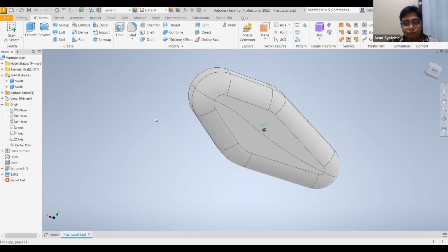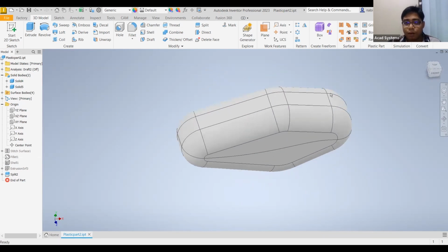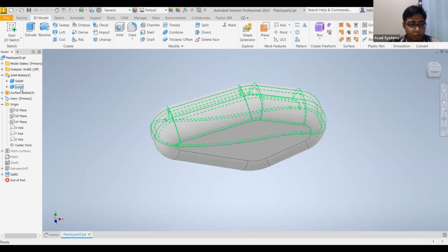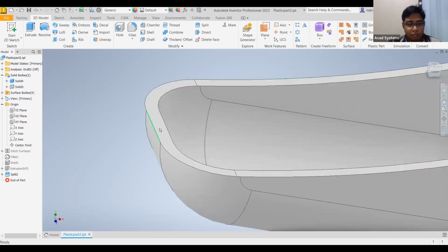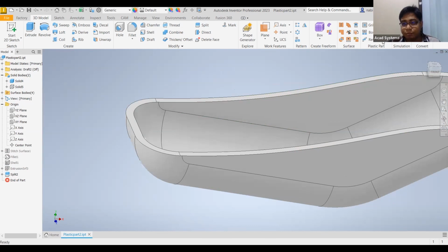Now that we have this cut into 2 areas, I'm going to apply the plastic tools. For example, I'm going to add connections so that this one can be snapped into the top of here, so it will be snapped together. So we're using the lips, and I'm going to tap this tool using a screw area. For that case, we can use boss. So I'm going to add the lips tool first.